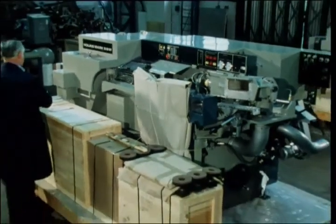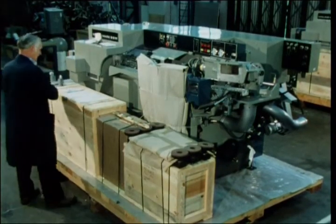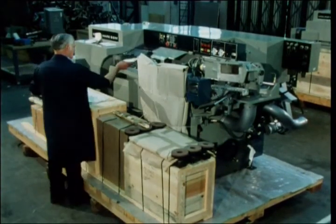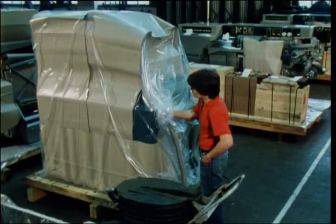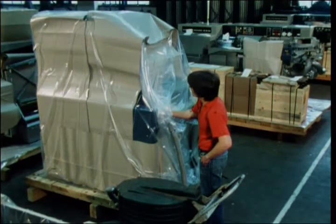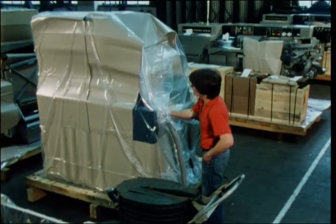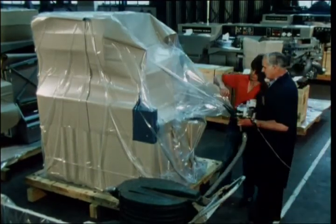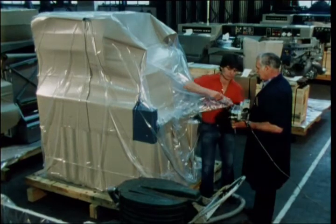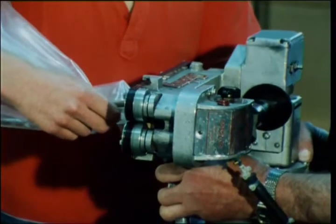Dry air can also be used in a slightly different way for the temporary packaging of machinery in transit. Silica gel packets absorb moisture, and the machine is completely enveloped in plastic. As much air as possible is taken out and the package sealed. This gives protection not only against corrosion from moisture, but from acids in the wood of the packing case.